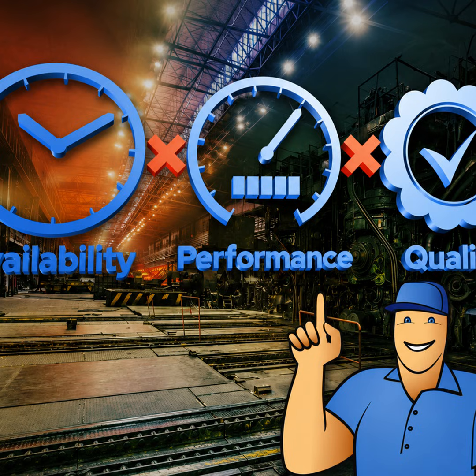2 other areas for opportunity are changeovers and startup scrap. Better organization for changeover operations could yield as high as a 30 to 40% decrease in lost time, often by just organizing the tools more effectively and standardizing the procedure. The best part is that it costs zero money. If you get a lot of scrap from tuning in your machines at startup, find out why. Check and see how your operators are adjusting their machines. I'm willing to bet that one operator has a system down to minimize scrap. Find out how, document it, and teach it to the others. Again, it costs nothing but the time to find out.